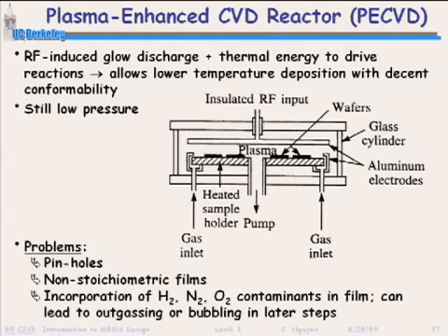Okay, so pinholes are bad news. And in MEMS especially, they're bad news. And that's why people shy away from PECVD for MEMS. This is one of the reasons. You can solve this by putting a very thick layer of PECVD down. But there's a problem with that too, and that's stress. Okay, the thicker that layer, the more stress problems you have.